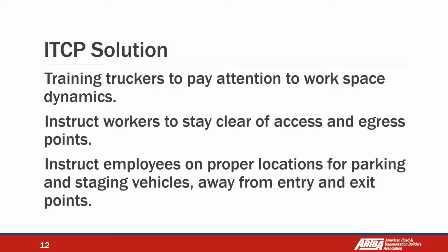Make it clear with workers: I don't want workers on foot in this area. This is the access zone. Okay, if you need to work in this area, the foreman, the competent person, should close the area and create another access zone. But we cannot allow workers, pedestrians, people, vehicles to be parked in the area, or machines working in the access zone area. Okay, it should be clear.